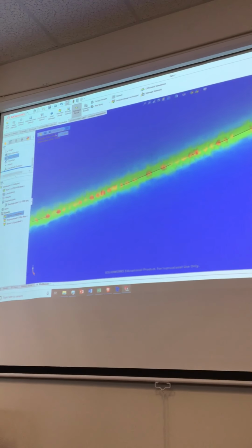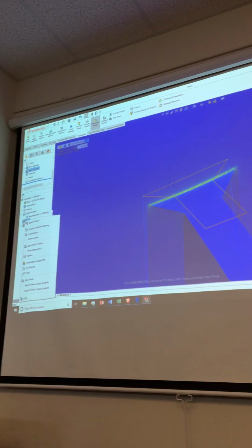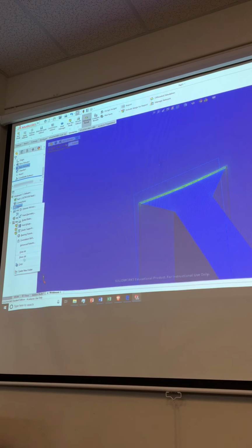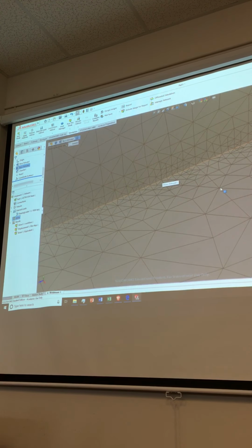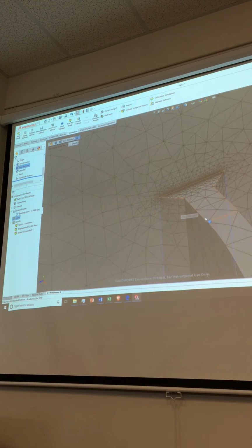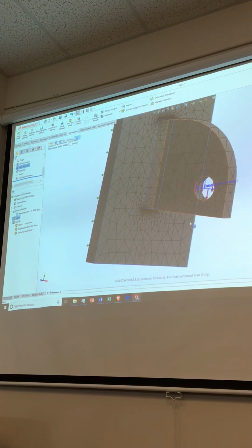And if we look at the mesh in here, let's just go show the mesh. First of all, we can look at the details of the mesh. I've got 100,000 nodes now. Started off with 2,500. And if I show the mesh, what do we see? I got a ridiculous amount of elements right in that groove, and pretty much no change anywhere else.